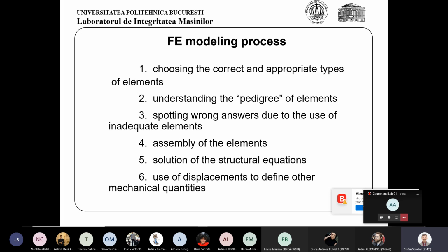So you will see sometimes the results are not good because the method is an approximative one, and if you make a bad decision when you take a finite element type, then when you use a mesh, the answer is not good. So you must keep in mind that and see where the results are not good and why, on some spot points.